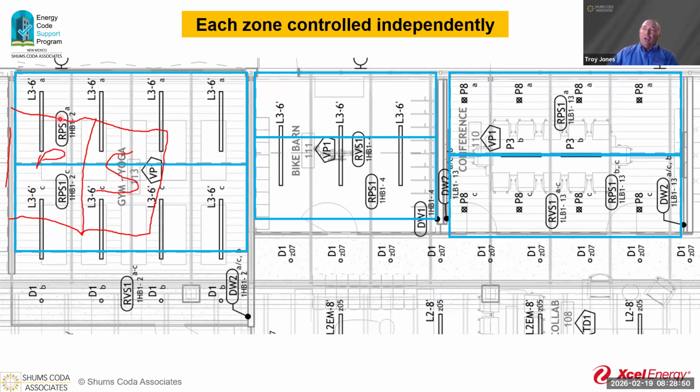These lights here are now in the primary section for this zone. So this occupancy sensor or this daylight responsive sensor here would be in control of this, as well as the secondary that's in control of this for this zone here. So it gets really fun when we have different zones overlapping each other.